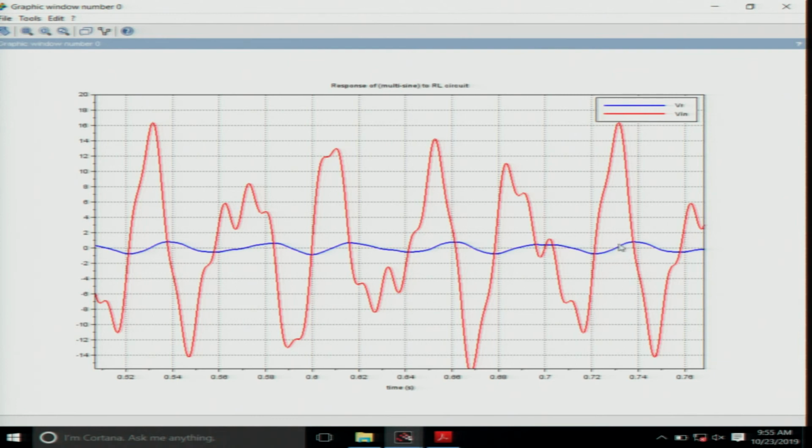So, you take the output signal, the output signal in blue, and you obtain the Fourier components of this. Now, Fourier components consist of DC. In this case, there is no DC. Remember that we have excluded the natural transient. So, the natural transient has died down, and what you have is a periodic steady state of 5 hertz. So, take 1 upon 5 hertz, that is 0.2 second window of this waveform, and actually do the integration of this waveform using the Fourier integral.